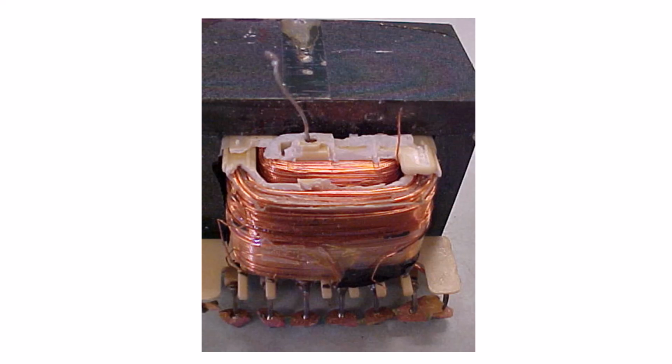Two coils of wire, current starts flowing down the one wire, it generates an electromagnetic field. The second coil picks up that electromagnetic field, which causes a current to start in the second coil of wire. This is the principle of mutual inductance. If the current is DC, once the magnetic field is established, it just stays static and it doesn't change, so the current will stop. But if you alternate the current, it goes one direction then the other, then back and forth, you're going to have an alternating current in the secondary coil as well.